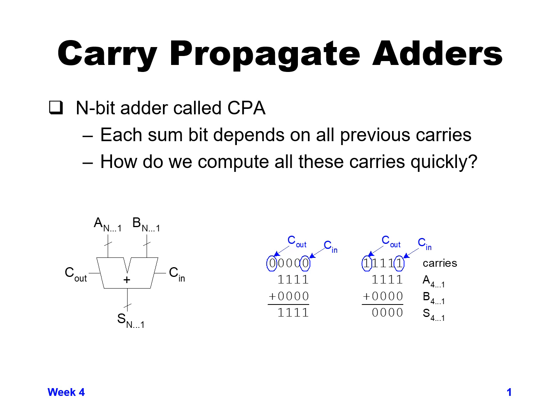Looking at the lower left, you can see the symbol for an adder. It looks like a mux structure, but has a little V in the middle between the two different inputs, A and B, each n bits, and then they are scrunched together to the sum of n bits on the output.